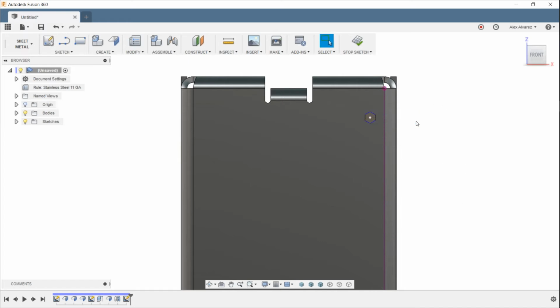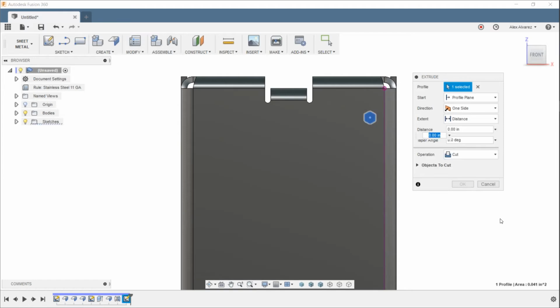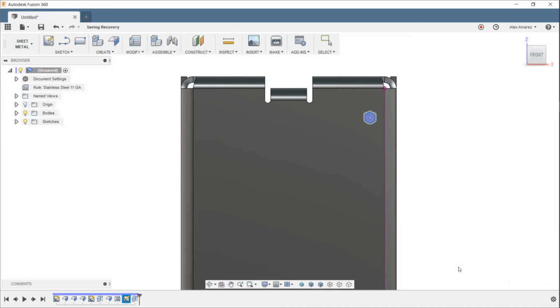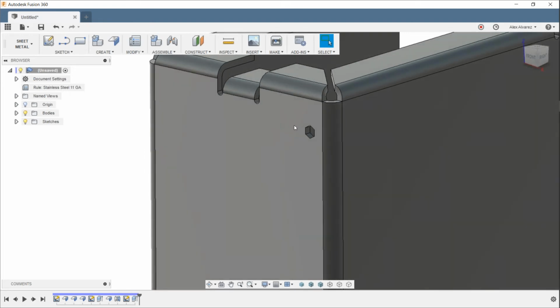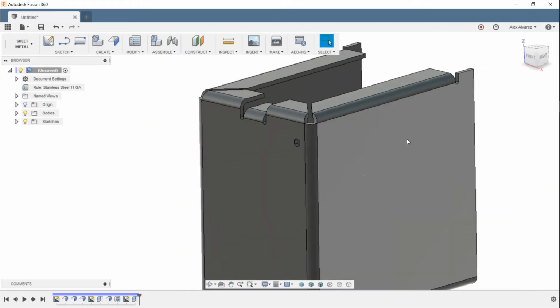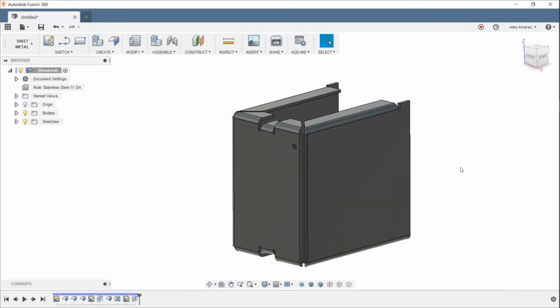All right, go ahead and extrude cut that and say minus D3, right? So again, sticking with that thickness parameter that we had. So minus D3, and it gives us the cutout. And again, if this ever changes thickness, that cutout is also going to change thickness along with it, right? So again, let's go ahead and pattern that.